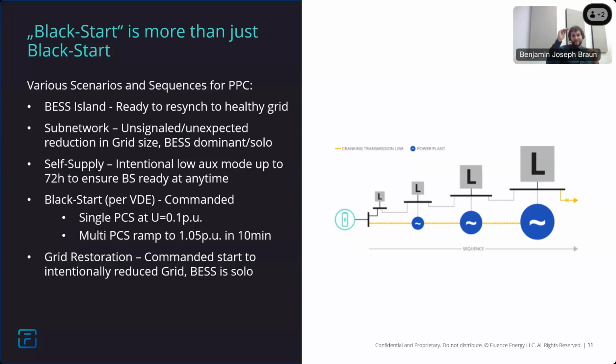As they start to bring voltage back up, they might see down the line with less load or with a distribution transformer tapped in a certain way, they might start to see an overvoltage down the line. To buy themselves some more time to react to such a situation, they require that actually we do a very slow ramp, so not just to avoid inrush, but really slow so that they can react better.